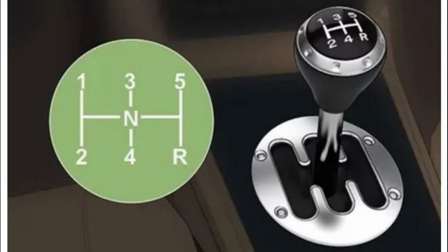Some automobiles are equipped with a continuously variable transmission, commonly known as CVT. Unlike manual or automatic transmissions, a CVT does not have fixed gear steps. Instead, it uses a system of pulleys and a belt or chain to provide a continuous range of gear ratios. This allows the engine to operate at the most efficient speed at all times. As a result, CVT-equipped vehicles do not have a specific number of driving gears, but rather an infinite number of gear ratios, along with a reverse function.